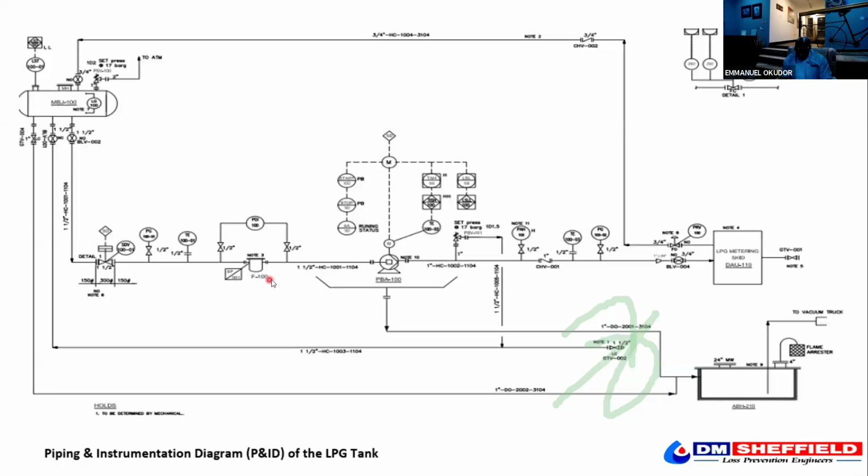If you look at this, this is a pump, API 14C, a lot of codes and standards whatsoever. A typical pump, you have what? A strainer. So this is a strainer. However, if there is liquid here, where do you now drain the liquid? Even here, there's no drain valve, the whole of this place. So for maintainability, there's an issue on this line here. So these are some of the things we need to look at.